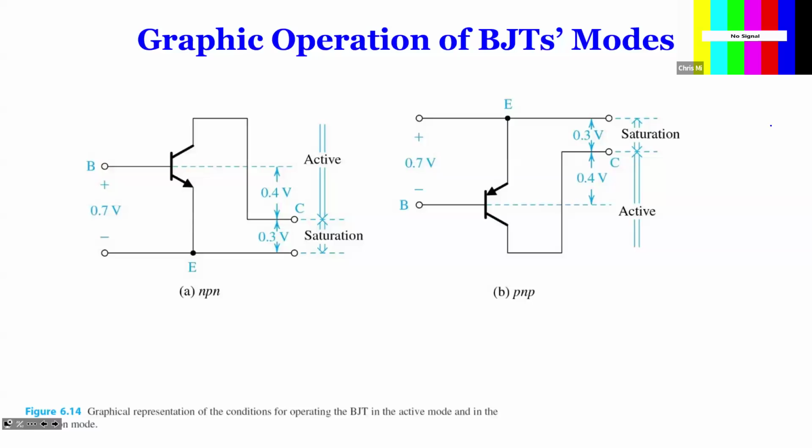Remember in the MOSFET, we did a little bit of threshold. You have to be above the threshold for the circuit to conduct. So we draw an illustration. Okay, this is the threshold, which has to be exceeded to work. But then your VDS has to be within a certain range. If your VDS is too low, it will go to triode instead of saturation mode.